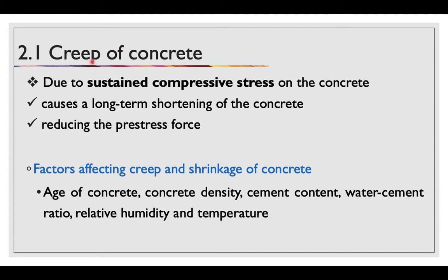For creep of concrete, it is due to sustained compressive stress in the concrete. It could cause a long-term shortening of the concrete, which could reduce the pre-stress force. So when we talk about creep in concrete, it will be undergoing long-term shortening, and sometimes this will cause our concrete structure to crack.